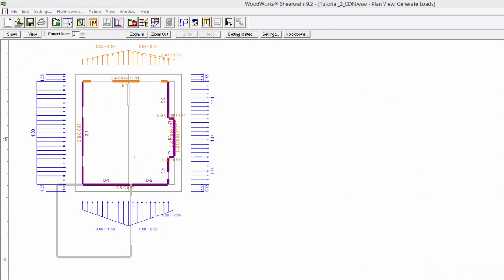This warning is to let the user know that this figure is typically used for flat roof, medium rise structures. We will proceed with the analysis as we have a multi-roof block structure and CP coefficients will be calculated based on the geometry of the blocks. The wind loads are now displayed in the plan view.